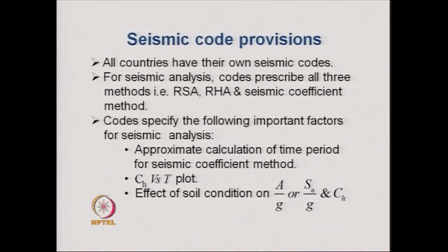These cases typically include the cases where we wish to study the behavior of the structure in the inelastic range. As you will see later, for most of the designs that are accomplished for structures for earthquake, we deliberately allow the structures to get into the inelastic range for the design earthquake level. Therefore, many a time the behavior of the structures in the inelastic range becomes very important. For those situations, the response time history analysis is an important consideration.